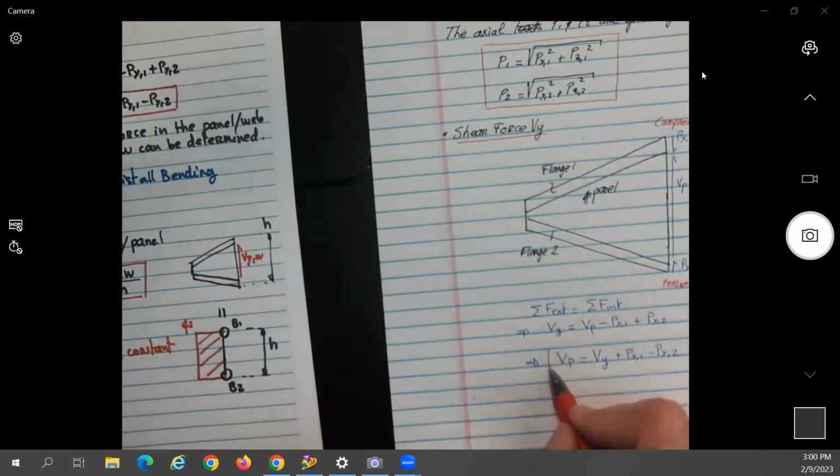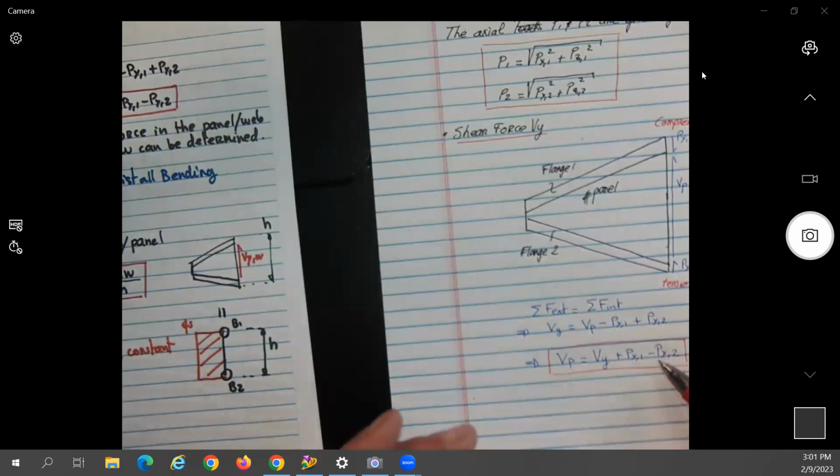So in the case, as you just mentioned, very good question, that you're doing up or down, what is that going to change? The math here will tell you if it's going up or down, no? It will be a different sign. But be careful here. I'd rather work with tension and compression, where I know exactly what's happening, than trust the signs, because there are so many switches in signs that at the end you don't know. Okay?